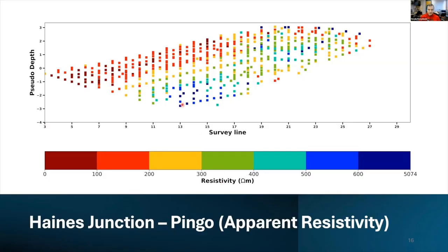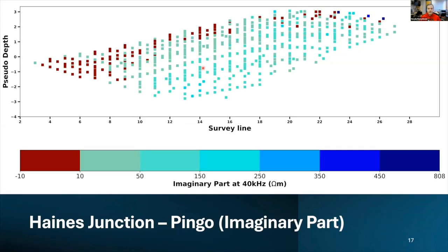So we can conclude that the resistivity cannot show really a good result for this field measurement because having 400 ohm meter is really low for ground ice, and the ground ice should show like the resistivity more than 1 kilo ohm meters.